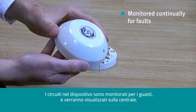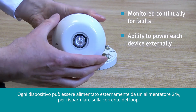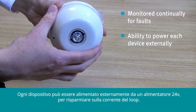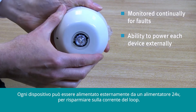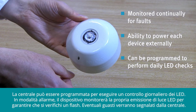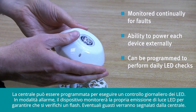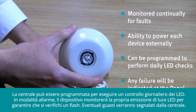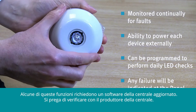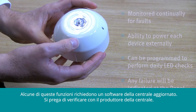There are many other benefits to choosing our new beacons. For example, the circuitry in each device is monitored continually for faults, which will show up at the panel. There is also the ability to power each device externally from a separate 24-volt power supply to save on loop current. The control panel can be programmed to perform a daily LED check, but also when in alarm mode, the VAD will monitor its own LED light output to ensure a flash occurs. In both instances, any failure will be indicated at the panel. Some of these functions are subject to control panel compatibility, so please check with your panel manufacturer.